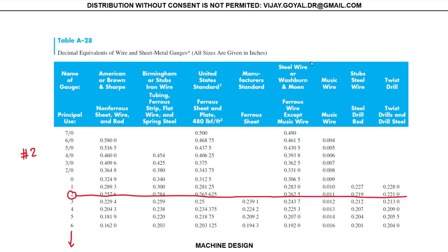Let's suppose I'm working with steel wire. This is the most typical one that we work with. Then you can see that the wire diameter will equal this. And if you're doing an iterative process, you just start at the diameter here. You can go gauge up, gauge down, depending on the case that you're working on.